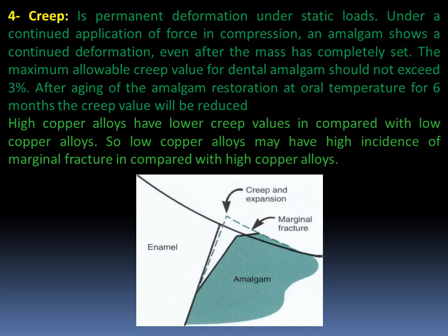Also, there is creep. It is permanent deformation under static loads. Under a continued application of force and compression, amalgam shows a continued deformation even after the mass has completely set, and the maximum allowable creep value for dental amalgam should not exceed 3% after aging of the amalgam restoration at oral temperature for 6 months.